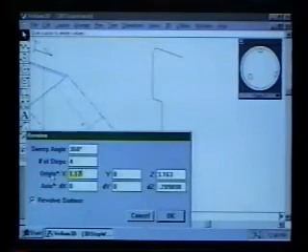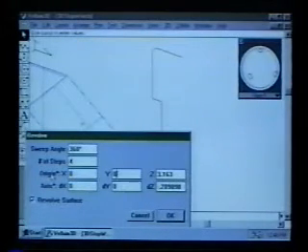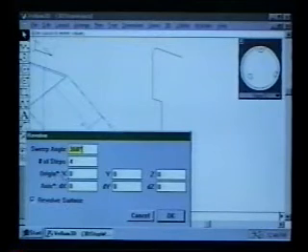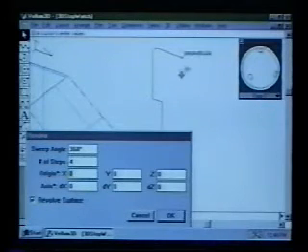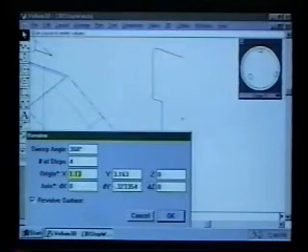So I don't have to type anything in here. In fact, when it first comes up, by default everything is a 0. And what we can do then is just highlight this box and go here and hit the enter, or pick this endpoint, press and hold, and pull a line right along that perpendicular direction, which will be in the current Y direction. And it fills in all my values for me.